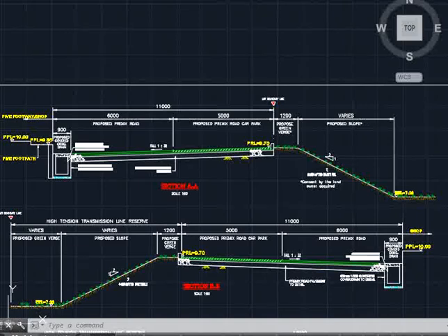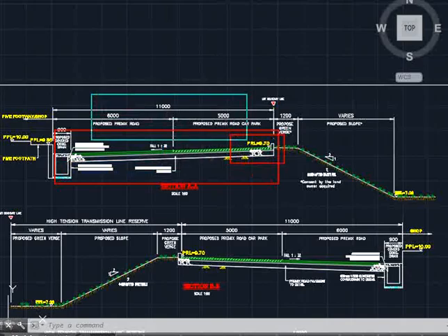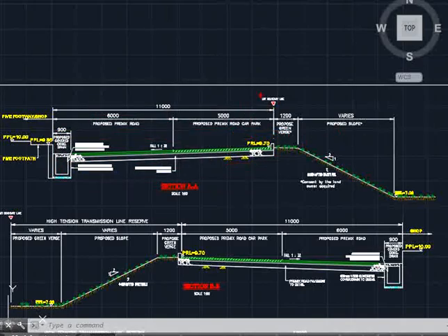In the previous videos, we talked about producing road sections as a part of the work in the engineering plan. It gives information regarding the conditions of the road and its surrounding areas. Among the important information include the proposed road level, the components of the road, the dimensions, the lot boundary, the elevations of the adjacent areas, the gradient of the road, as well as the slope.